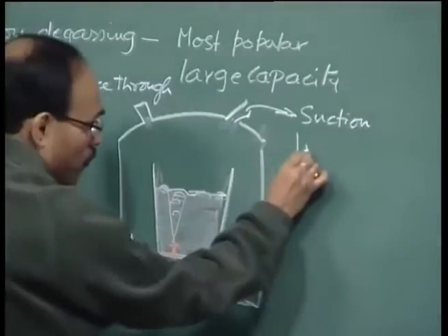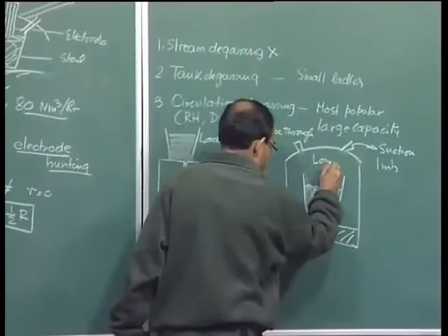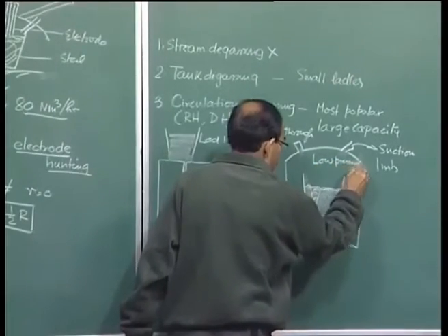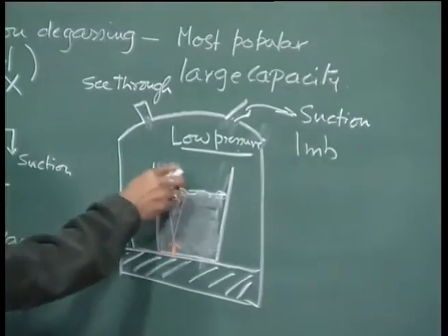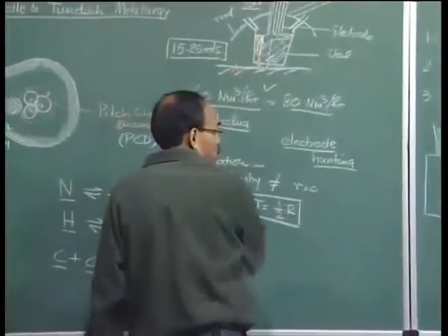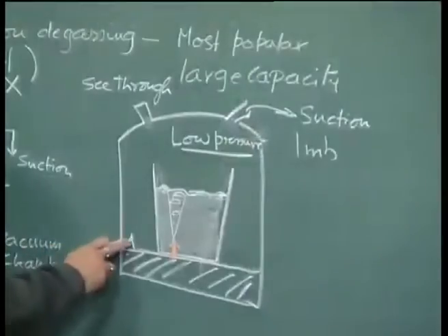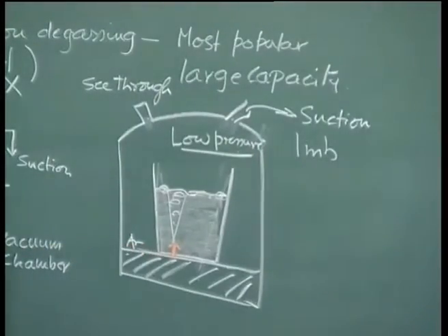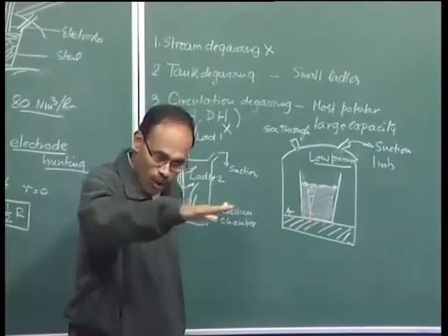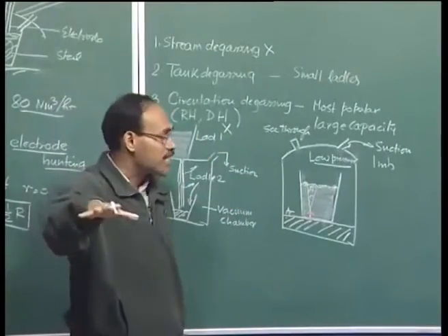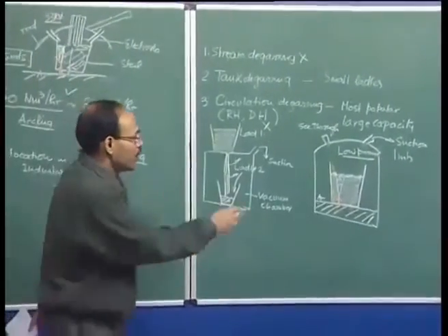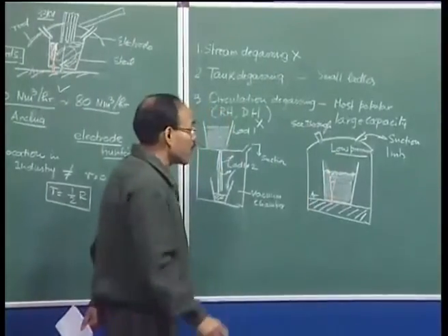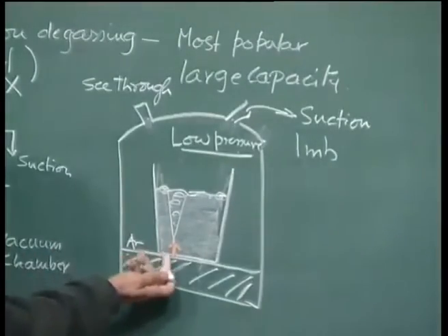and this produces a low pressure system, as a result of which fresh material is going to be exposed to the low pressure, and there this particular reaction is going to be facilitated. We must understand that without argon, the scenario we are going to have is molten metal covered completely by slag. So, we want to bring molten metal in contact with the vacuum or the atmosphere, and as a result we have to blow in argon.